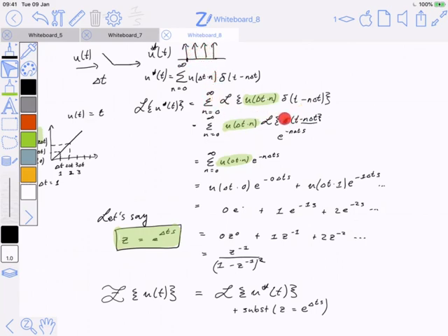And so when we do this Laplace transform, every time we see a Z, and especially this is why we favor these negative powers of Z, is because when we're talking about causal systems, we always want to be referring to the past. And so you'll see the textbook and quite a lot of control literature favors the negative power of Z form because it's got a nice interpretation. It's a back step. So Z to the power minus 1 is like take that thing and talk about the value of that thing but in the past.